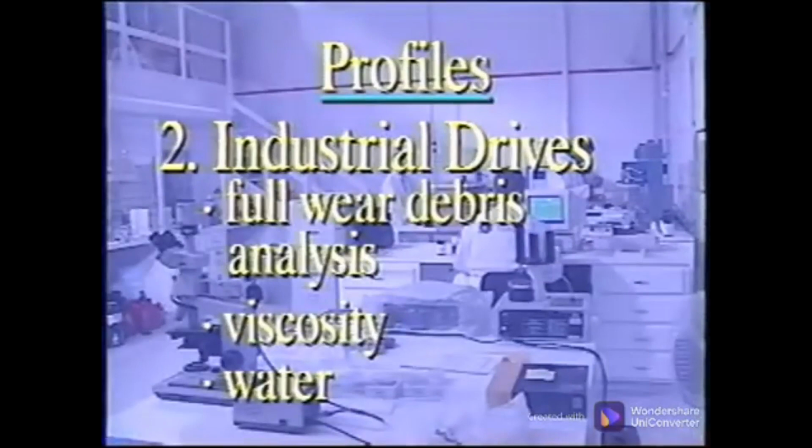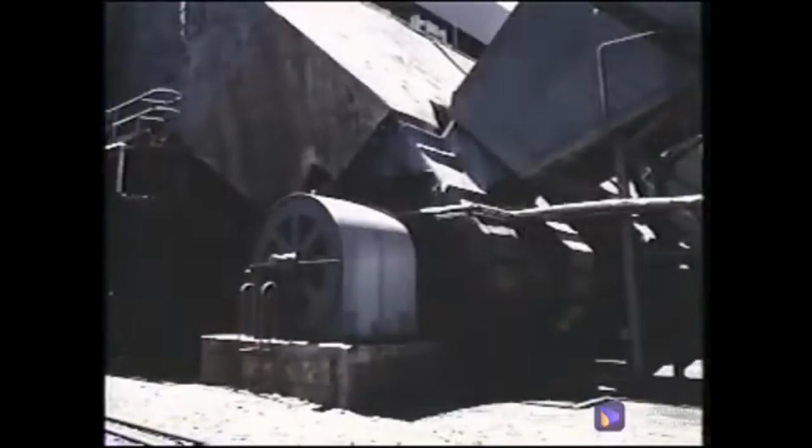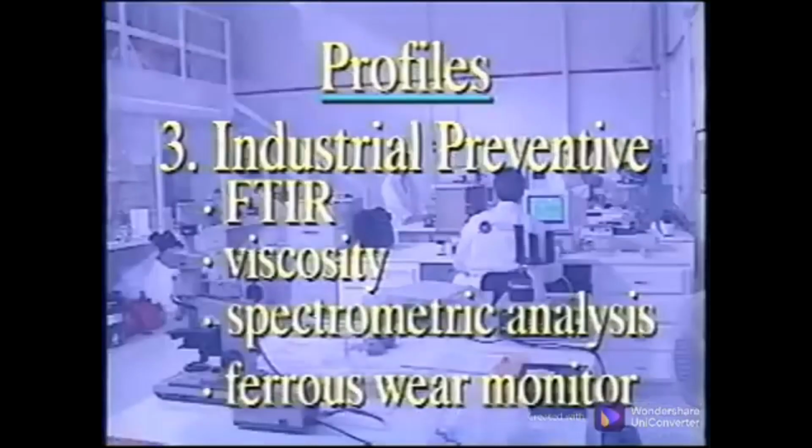Off-site analysis should include a full wear debris analysis, viscosity, water contamination, spectrometric oil analysis for the additive condition, and the FTIR to determine degradation. The industrial preventive profile includes common pumps, fans, compressors, and engines. Tests should include all measurements the 5100 analyzer performs for contamination, degradation, and wear. The lab test should be the FTIR, the viscometer, spectrometric oil analyzer, and the ferrous wear monitor.